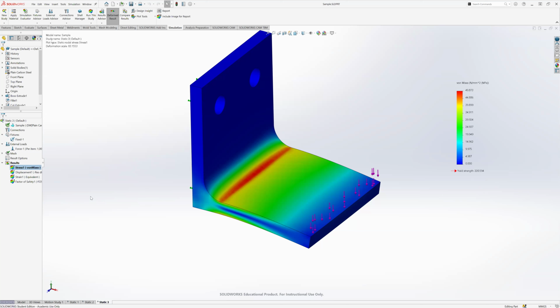Okay. So next time I'll try to go over something called mesh controls. If you need to make meshes finer in certain parts, you may not want a super, super fine mesh everywhere. You may want to put a fine mesh in just certain areas. So that's what I'll go into next time. But if anybody has any questions, I will go ahead and stop recording now.